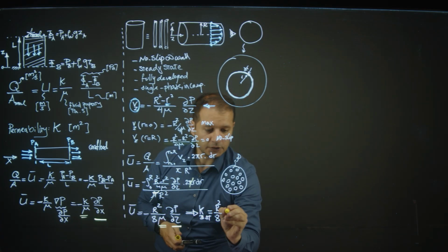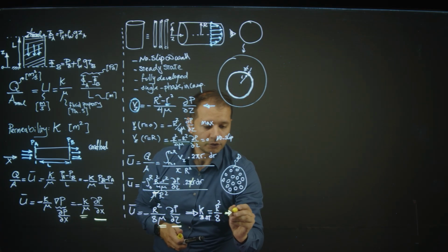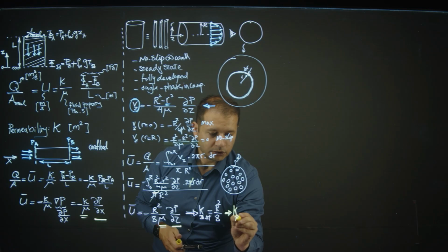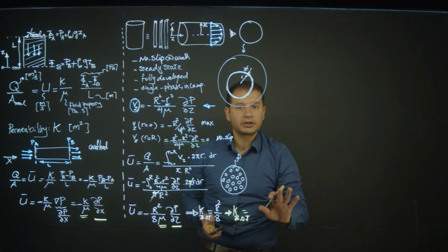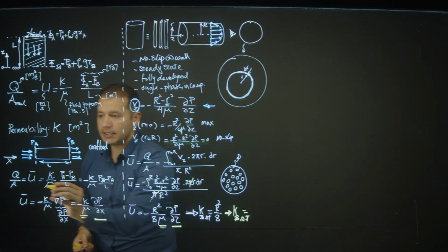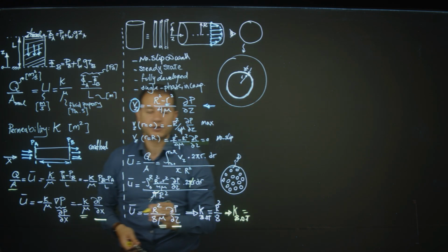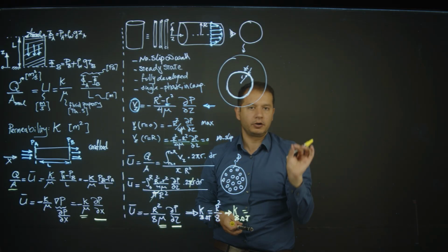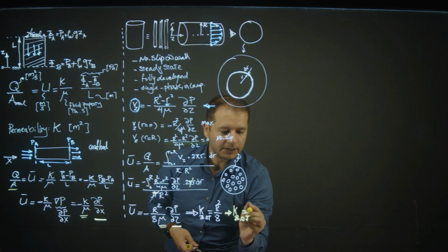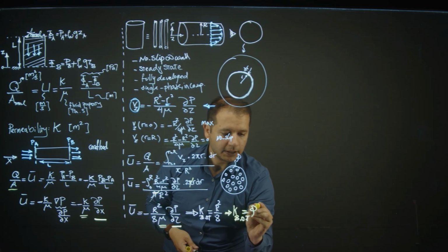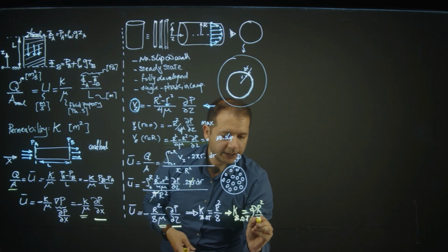Then the bundle of tube says that your K would be the volume fraction available for the flow compared to the total, because velocity of the Darcy is divided by the total cross-section area and not just the pore volume cross-section area. And in that case, the bundle of tube would say permeability is φ R² over 8.